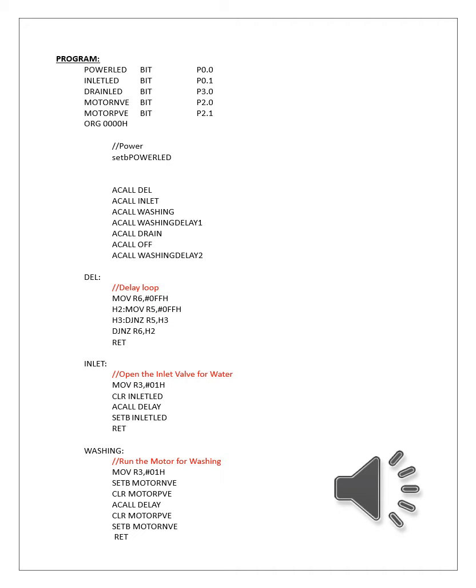What is R3? Here, if I give 0, 1, that particular delay will run for 15 seconds. So 1 into 15 seconds it will run. Automatically, if I give 2, that delay will run for 30 seconds. So for the multiples, we are loading R3.